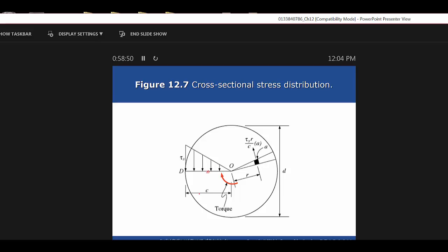2.48. Okay, so that's just a little bit under 2.5, right? But it's more than 2.4375, which would be 2 7/16, right? Well, you wouldn't want to buy the 2 7/16 diameter shaft. You'd want to go to the 2.5. So I think that's what's pertinent about that table. You're only going to be able to get it in increments of 1/16 of an inch. So if it's somewhere between 2 7/16 and 2.5, you need to step up to the 2.5.